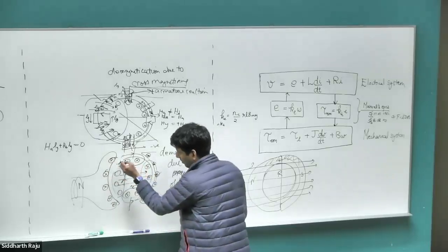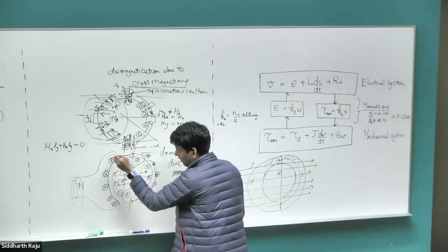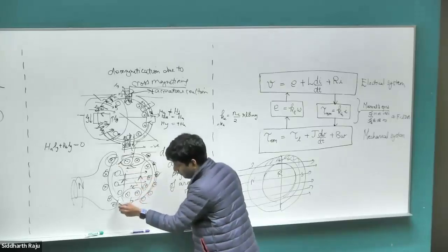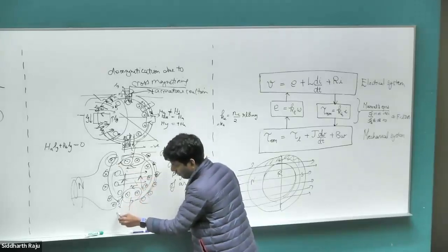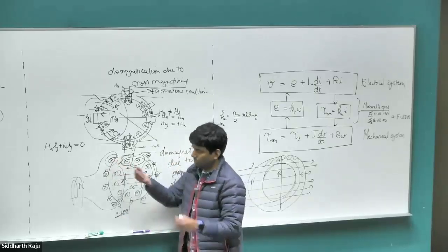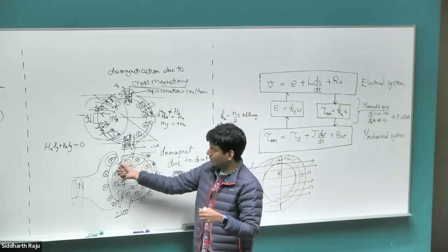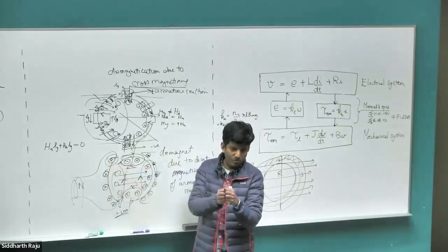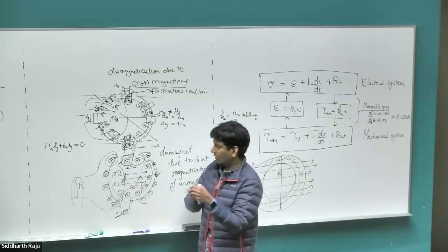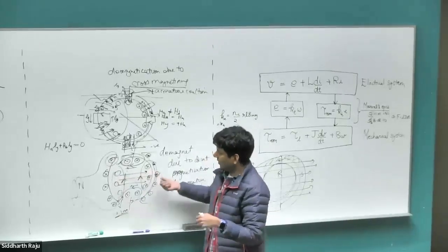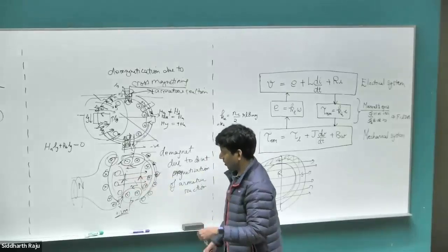So what then happens is whatever field lines this conductor is creating, it's going to be cancelled out by field lines of this conductor. Because again, these are exaggerated air gaps. This distance is extremely tiny. For a high power motor, 0.2 millimeter or lower is very typical. So this is as if these two conductors are placed extremely close together. If this is carrying current in one direction and this is carrying current in the opposite direction, the B fields are going to cancel out perfectly. So once we cancel out those B fields, there is no effect of this demagnetization effect, right? So we don't have this direct demagnetization effect caused at all.